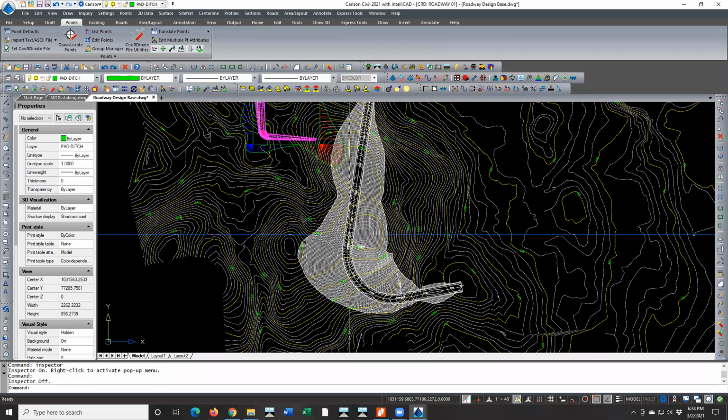I don't use K values for verticals, but even on the horizontals, I can visualize a curve better if I see the tangent distance instead of the curve distance, because I know where my PI is. So I can estimate my tangent distance back and ahead of that PI, and that tells me where my curve's going to start. Other people say, the curve I want is such and such a radius, but I don't know what that's going to be until I try several and look at it. So it's just a difference in perception.